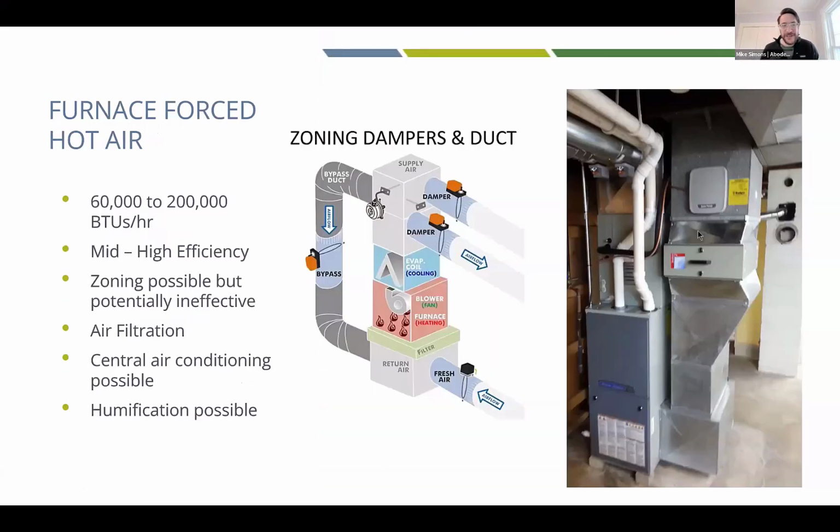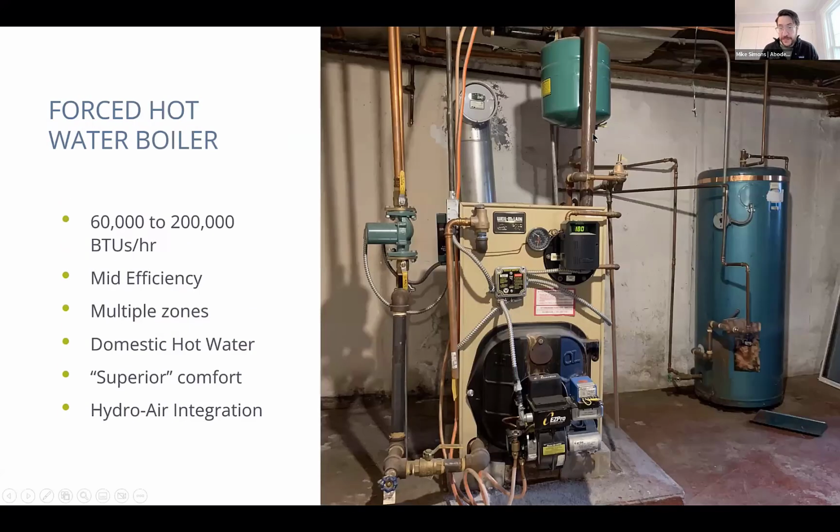Okay. So now we have a modern forced hot air furnace, and let's look at a few different things because some things have changed that are worth highlighting. Over here, the flue pipe was metal, and if I were to measure the temperature of these exhaust gases, they'd be somewhere around 350 to 500 degrees, which I think is remarkable because lots of households argue between, say, 68 degrees and 70 degrees.